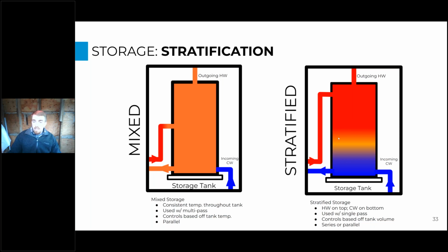What we're going to see is as hot water is drawn out to the building and cold water is brought in the bottom, now cold water will start to fill this tank from the bottom up, and this little yellow layer here will be sucked up to the top of the tank as the hot water is drawn out the top. So this sensor located right here will go from 140 degrees down to 50 degrees in a really short period of time. So we're going to tell the heat pump to turn on based off this temperature sensor dropping significantly in temperature. And so that means the location of this sensor is really important, because if we don't turn it on until the sensor's cold up here, now your entire tank's empty before your heat pump turns on.